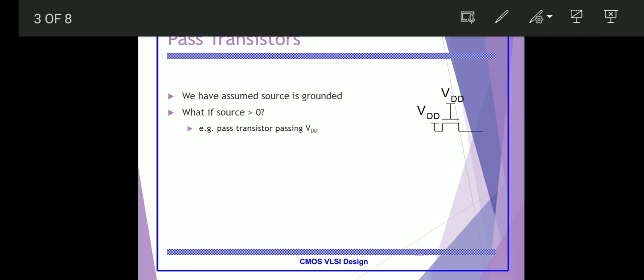As discussed, NMOS devices are effective in passing a strong 0, but are poor at pulling a node to VDD. Hence, when the pass transistor pulls a node to high logic, the output only changes to VDD minus VTH. This is the major disadvantage of pass transistors. Also, these applications use fewer transistors that can run faster and require less power than the same function implemented in other ways.